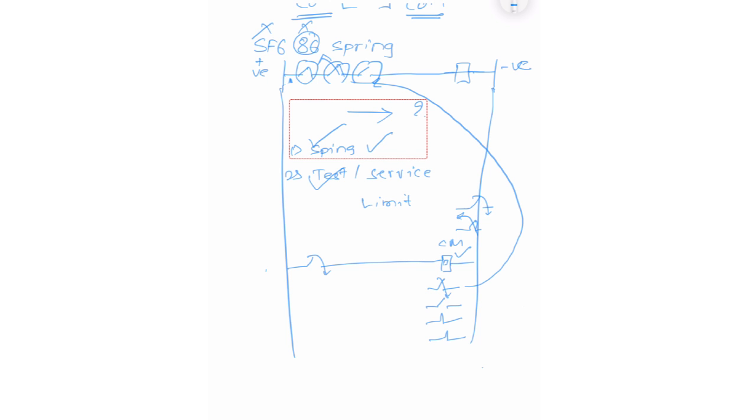There is another condition checked for breaker open or close condition. How is that checked? If we want to close the breaker, then we will ensure that the breaker is already open. Why is this condition necessary? This condition ensures that the command will get through for a momentary period. If we are trying to close the breaker, then the command will drop as soon as the breaker is closed. So this contact is taken either through a contact multiplier or directly through a mechanical arrangement.